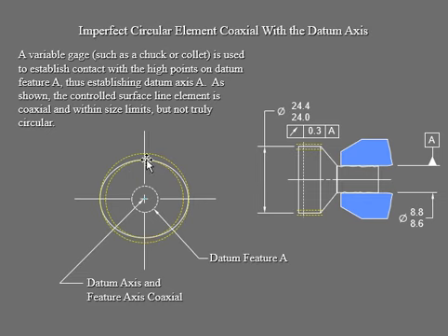So your yellow, as usual, is your datum axis right here, and your feature axis also. They are sharing the same axis, so we have a coaxial, and of course your datum feature A is going to be right there, because see where this symbol is standing on that surface, which is your smaller concentric circle right there. And then of course here is your true runout, which is this diameter right here. And then the zone we can see with the yellow zone right there.